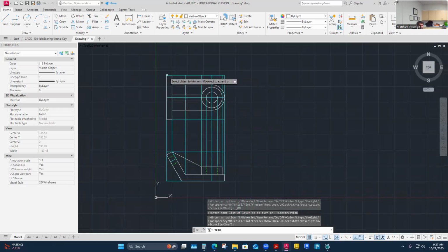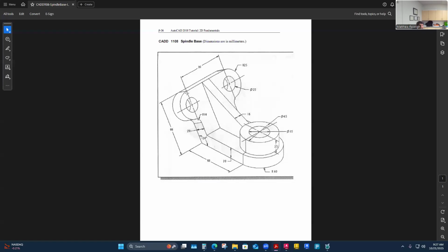Feel like I'm going to start with the outer radiuses here and then worry about the holes last, but I'm kind of worrying about the big radius ear features. I might consider those kind of like the ears that stick out and then how they go back in. So I'm going to worry about this kind of ear, and I think I'm going to project up from the front view to do that. And then I've also got a radius of 10. So I've got the big ear, and then when it radiuses back into this 80 millimeter wide area here, I've got a radius of 10 here.